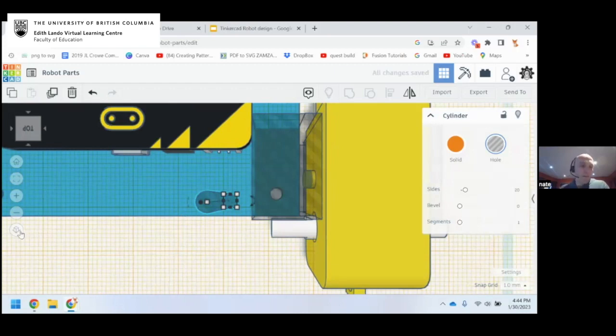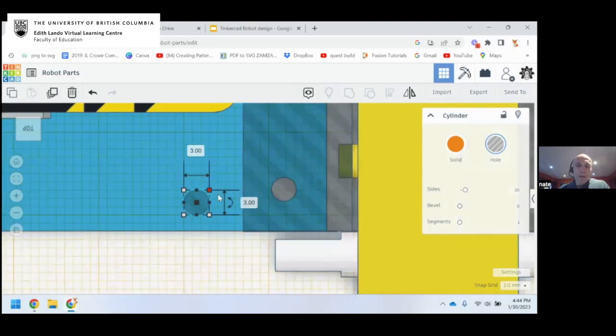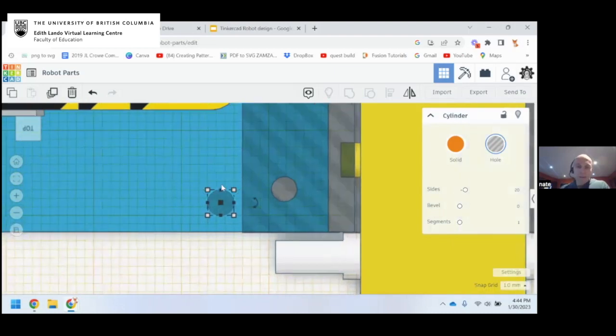So I'm going to click on the orthographic view and use the arrow keys on my keyboard. I'm going to move over and I'm going to move up. Now you notice with the arrow keys, I can't get it exactly to where I want it, which is pretty annoying. And this is where we get into turning off the snap. So I mentioned the snap at the very start. So if we come down to the, I'll close this up.